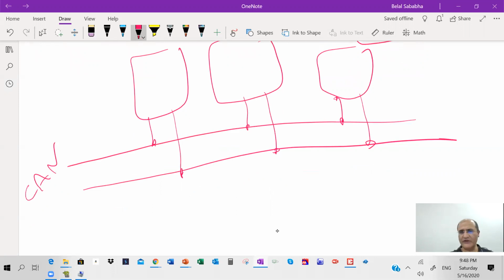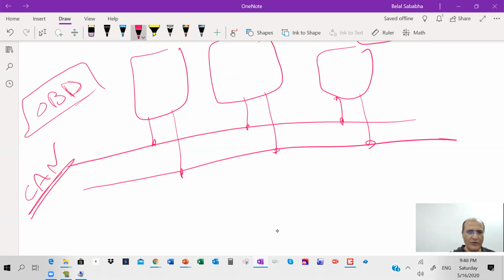It's usually between 60 to 150 controllers, all connected through a network. You call it a CAN network. When you go to the service shop or you have a check engine, you connect the OBD. The OBD is connected to the CAN bus, and it sniffs the messages here, and depending on the message ID it reads, it knows what the fault is. Anyways, it's not our topic.